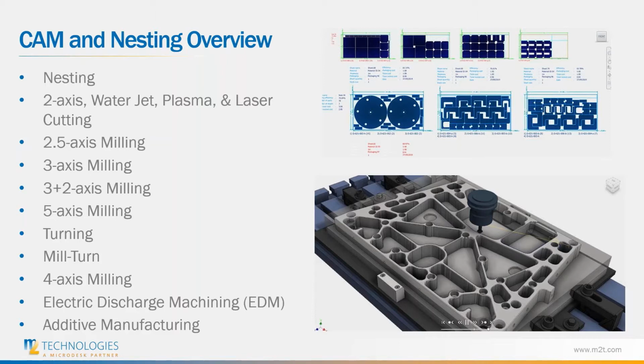Next, we have our 2.5 axis milling. 2.5 axis milling is a type of 3-axis milling, but rather than having fluid transitions between the 3 axes, 2.5 axis only works in 2 directions at once, so often works by working down through material in layers.